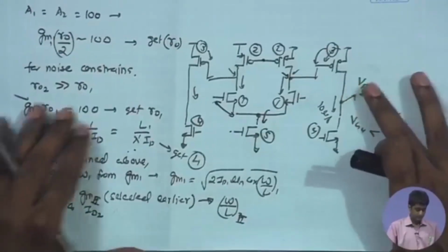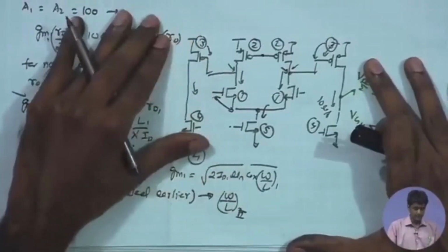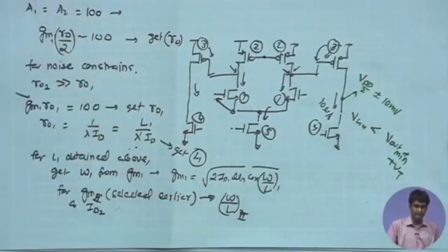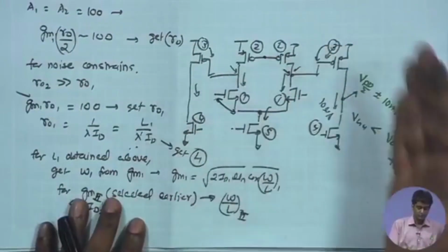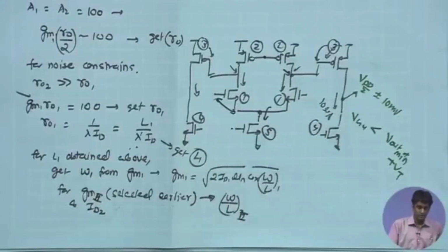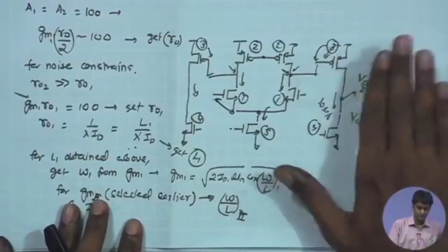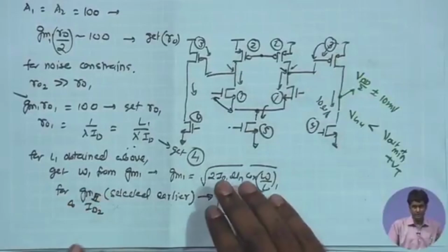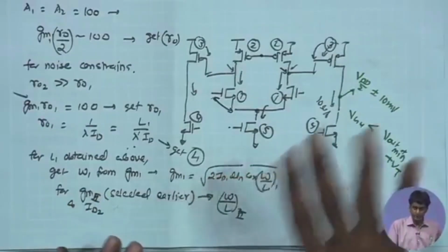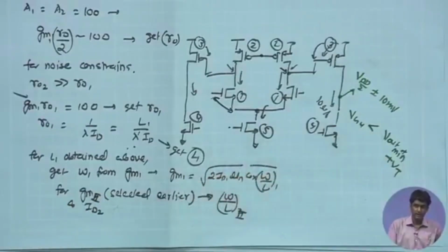Another issue that we have is the common mode feedback amplifier. There we have already studied that for the common mode feedback amplifier, if we are going for a single loop and we are using the diode connected load for the error amplifier, the gain requirement is not so critical, and therefore the W by L and bias current can all be relatively lower, the sizing constraint can be relatively lower.